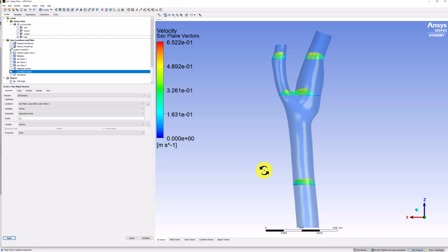As we move closer to the fork, however, the symmetry is lost. The velocity becomes much higher near the inner walls, and the profile becomes skewed. As we move even farther towards the outlets, however, the profile has generally recovered to the typical symmetric profile, as is typical of pipe flow. This matches our expectations from pre-analysis.